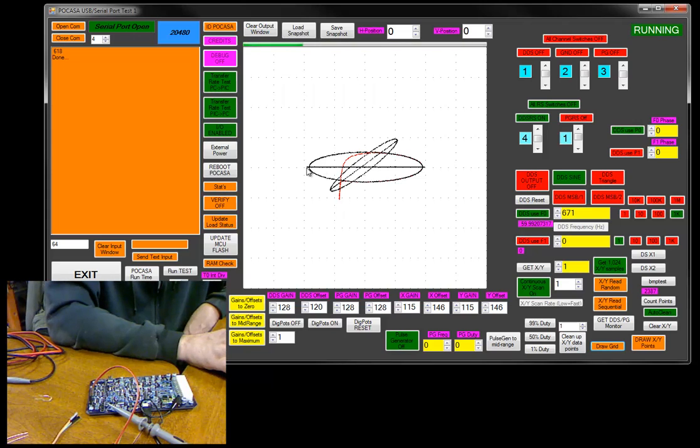If your gate is at 0 volts, you're going to get a flat line there. When you turn your gate on, you throw a couple of volts on, it's going to go up and down. And if you just happen to pulse it in the linear region, you'll get somewhere in the middle there if you're not saturated. And same thing goes with the transistor.